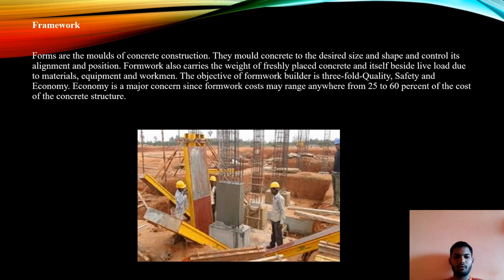After that, framework, or formwork, is a module of concrete construction. It molds concrete into the desired size and shape and controls its alignment and position. Formwork also carries the weight of the freshly placed concrete and itself, besides the live load and the load due to material requirement of the workmen. The objective of the formwork builder is the threefold quality of safety, quality, and economy.